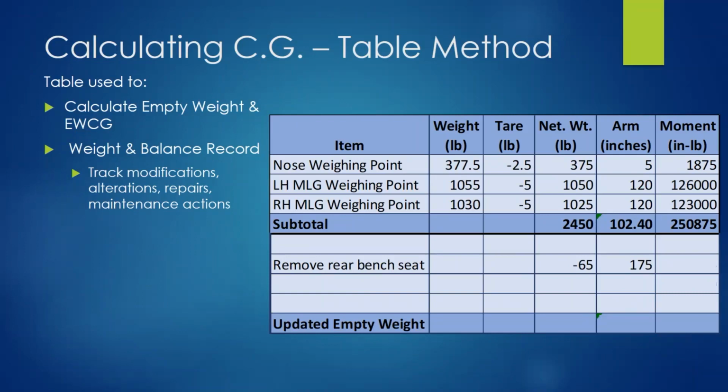There's actually two places we could probably find it. Not the maintenance manual. The TCDS is going to list the location of the rear seat. What's the other one? The equipment list. Remember that aircraft equipment list I showed early on yesterday? It shows the installed, the optional, the replacement equipment, the different types of equipment. So that's another spot you could get this.